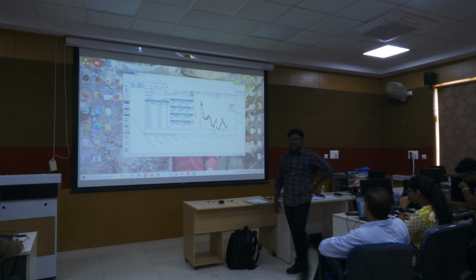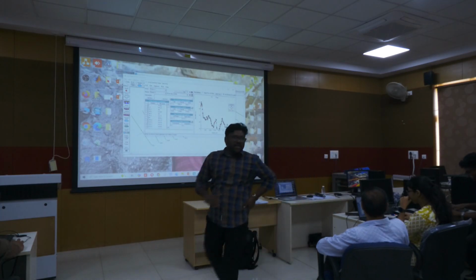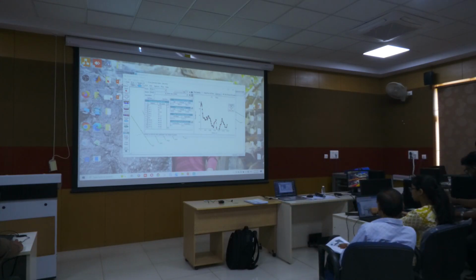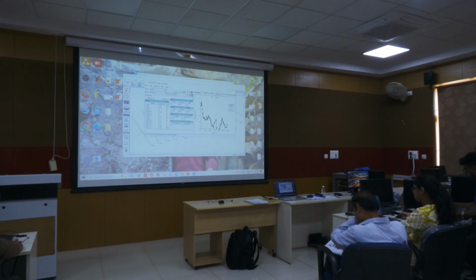Once done, cross check whether you have done it for all the cross sections or not. We are not giving the roughness value along the cross section, so you are eliminating it. But along the river, we should give it. The floodplain also, what is that?